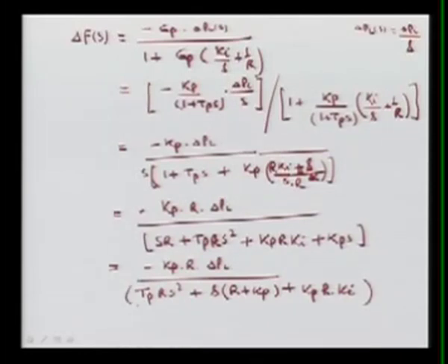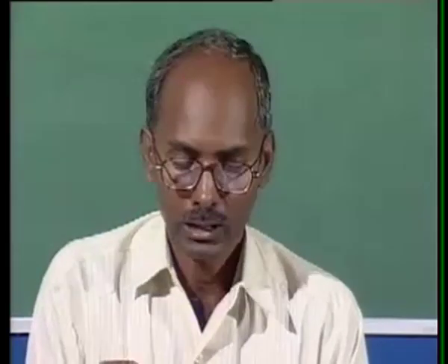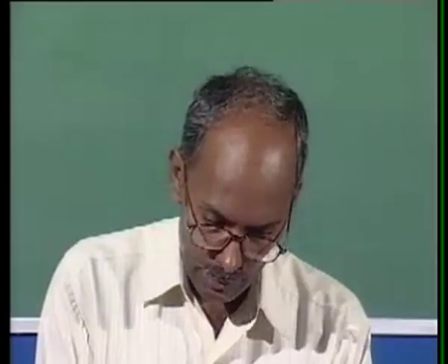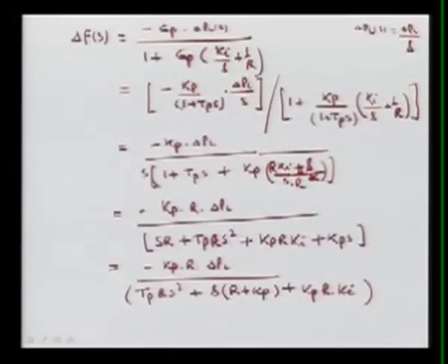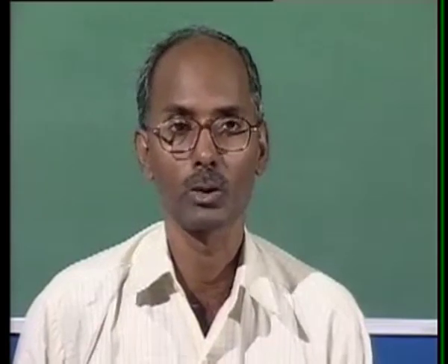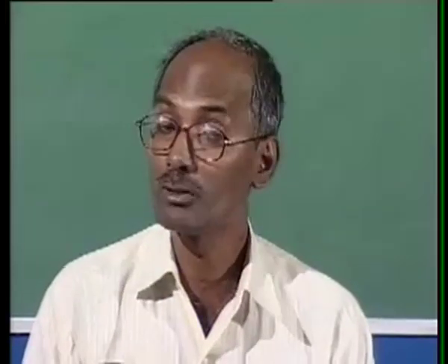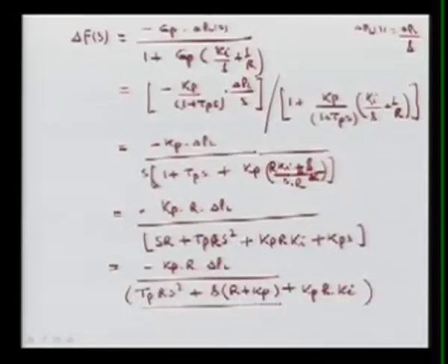Now we can see this denominator is a quadratic equation, which means we will have two roots. Tp and T are fixed, because they are related to the already designed parameters. Once the governors are set they are constant, but Ki, the integral gain, we can change and set for our system performance. The characteristic roots are very important to decide whether your system is stable or not. The first criterion we have to meet is that we have a stable closed loop, meaning this loop is stable.